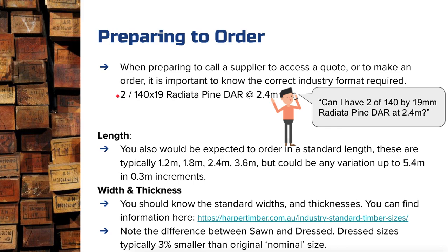The biggest issue that I find, what I've found in my experience, is that students, when they're doing their total lengths, forget to account for the length of the timber used within joinery. For example, they may forget that they need to add 10 millimeters to the length of a timber for a 10 millimeter housing joint. Or they may forget that when you use a dovetail joint, you need the full thickness added to the length. Okay, so there's a few little finite details there that we know from experience and logically make sense, but if you're not looking for them, it's very easy to forget. So getting a second set of eyes before you move forward with ordering your timber is strongly recommended.